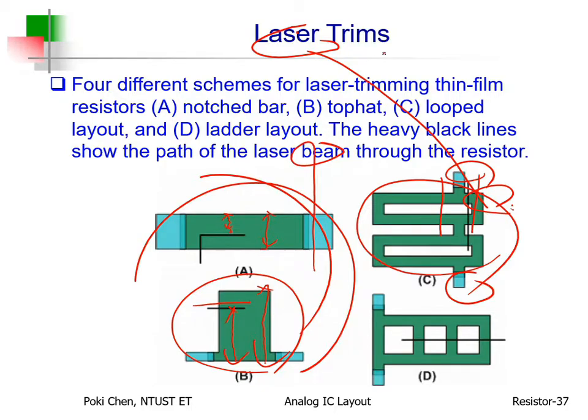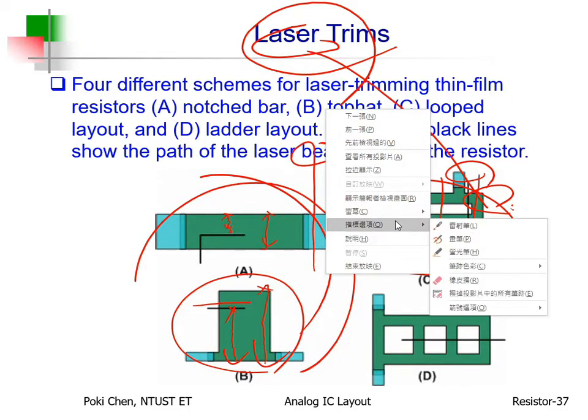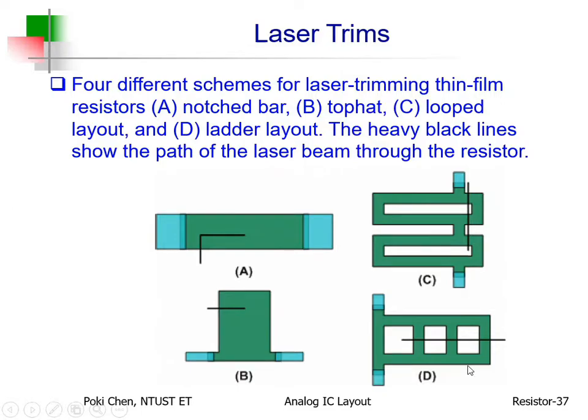But nowadays, according to calibration, we almost don't use any kind of laser trimming. It is very expensive. And sometimes it would go wrong because for such laser trimming, you try to use the high energy laser to vaporize this area and that area. But after that, you need to cool it down.